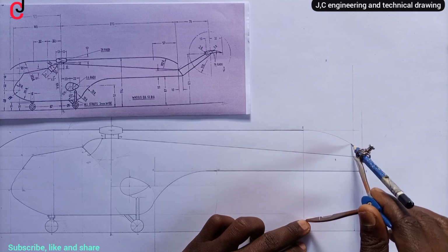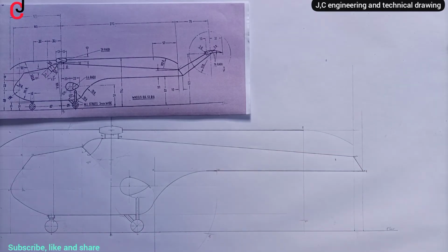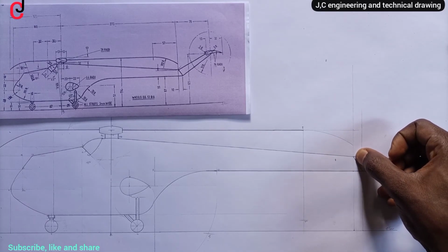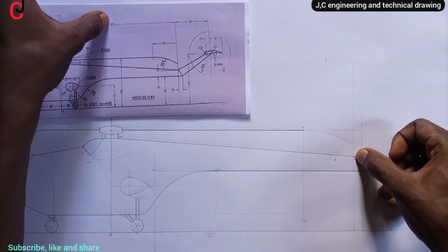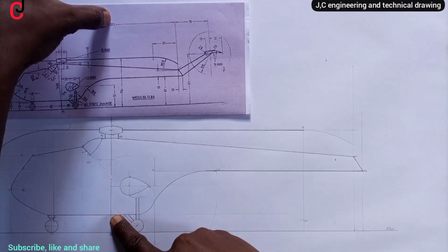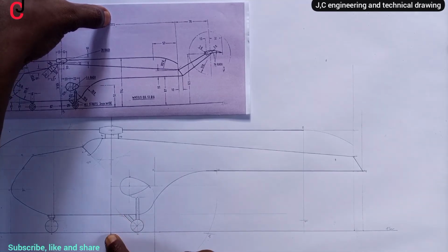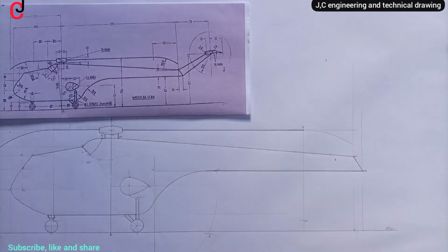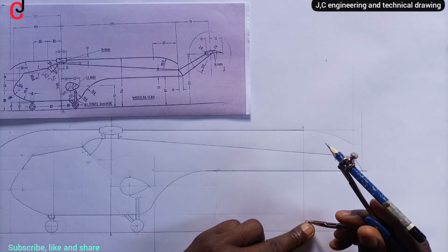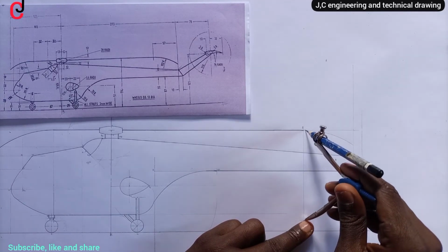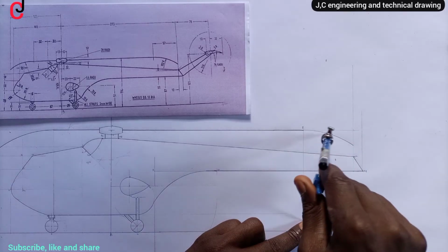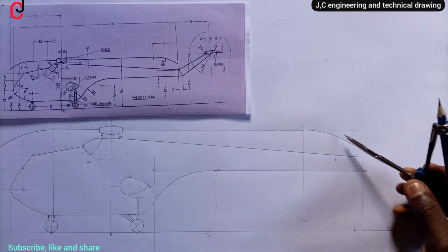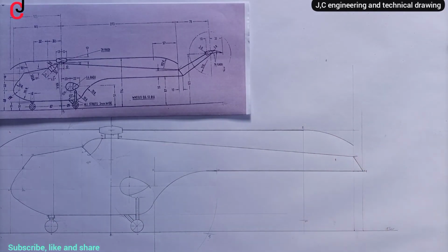We'll draw an arc. Once it hits a horizontal line here, which is touching point X2, which we got as 273 millimeter distance from our center vertical line. From here, point B to this line here is 273 millimeter. So once it hits that line, it will stop. You can see, outline this. Once it hits, we'll stop, make it an outline, and you see we are done with the wing aspect of our helicopter.